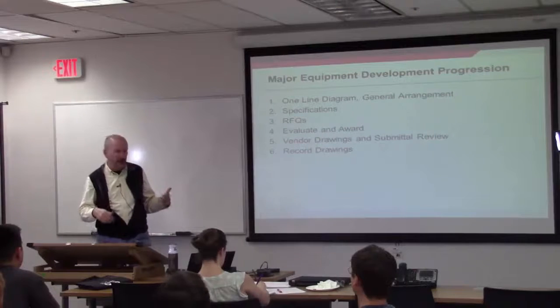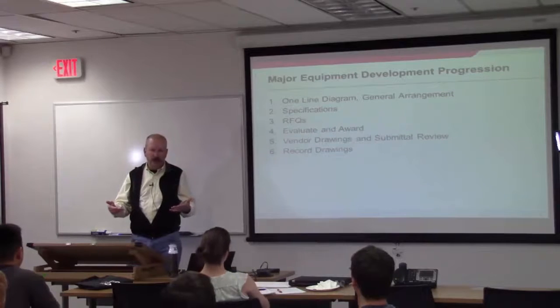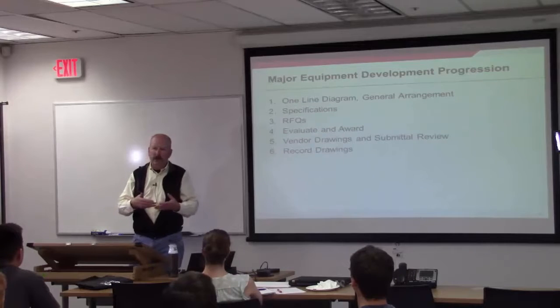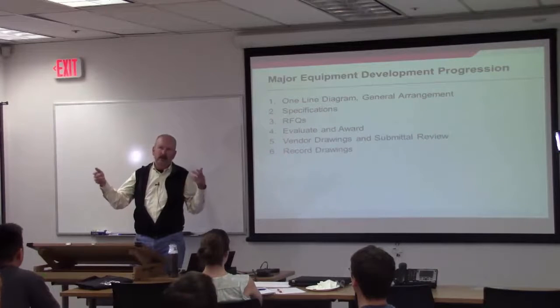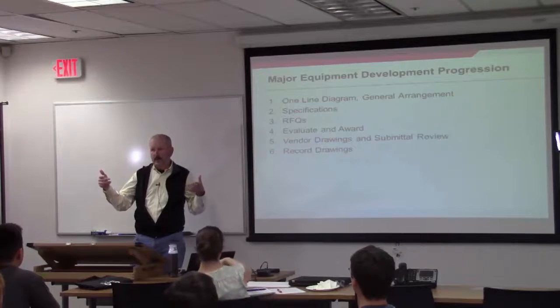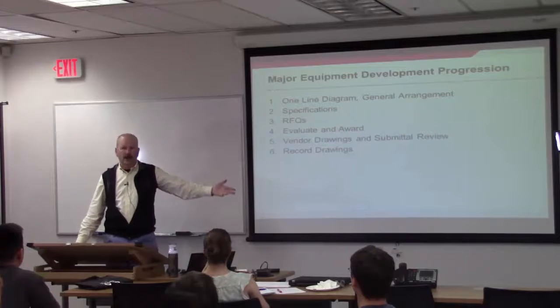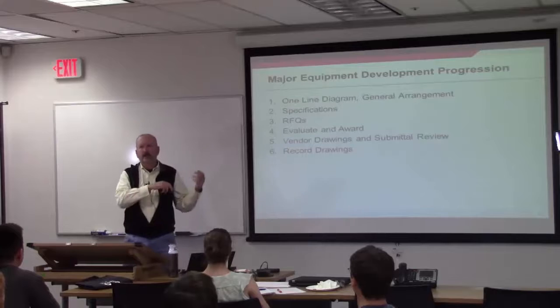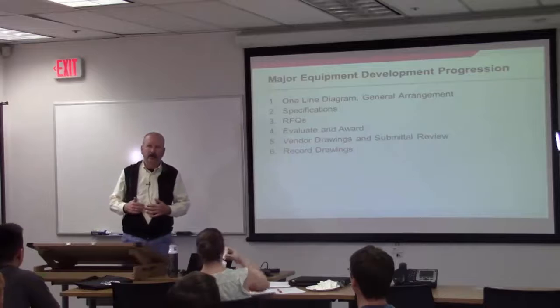So for all these projects, ideally, we're going to sit down before it goes out and gets issued for construction and have someone check the whole thing, make sure it's like a giant puzzle where all the pieces have to fit together. Design busts generally will happen if the people conducting the design don't talk to each other and aren't aware of what each other is doing. For instance, if someone has lost track of where the vendor drawings are for the circuit breaker and they use the approval drawings in their design, as an example, not that I've ever done anything like that.